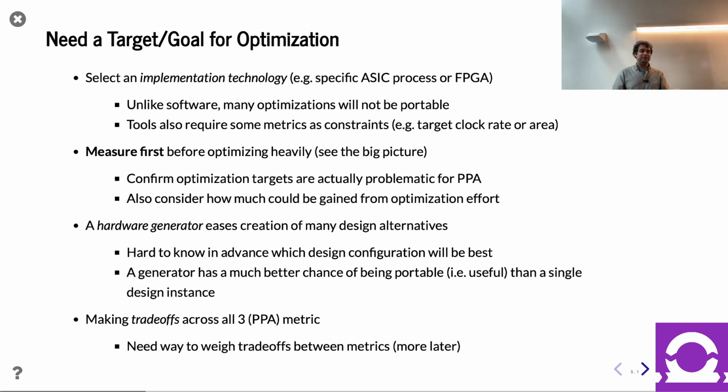And you can imagine how, gee, if I had a generator, boy, would that be an easy change, right? Oh, I want to change the amount of bits in my exponent and my mantissa. That's like a two character change. Boom, done. Go Chisel, do it, right? That's perfect. Alternatively, the block floating point is an opportunity to recognize you have multiple numbers going at the same time, so they actually can share the exponent across multiple floating point numbers at the same time.